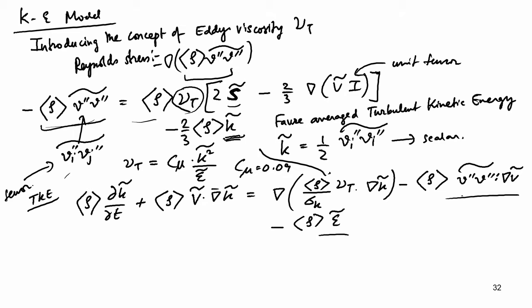So, that is the kinetic energy transport equation, for which you essentially need a closure for the previous Reynolds stress terms, the eddy viscosity closure. It can be essentially an exact equation with some model constants because of the introduction of these things. But the next equation is the epsilon equation, the mean turbulent kinetic energy dissipation rate.